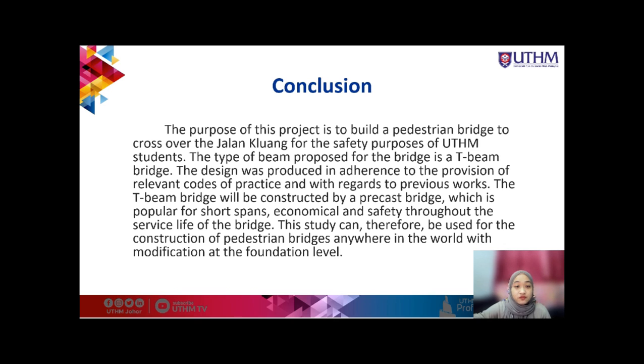In conclusion, the purpose of this project is to build a pedestrian bridge to cross over Jalan Keluang for the safety of EDHM students. The type of beam proposed for the bridge is a T-beam bridge. The design was produced in adherence to the provisions of relevant codes of practice and with regard to previous works. The T-beam bridge will be constructed as a precast bridge, which is popular for short spans, economical, and safe throughout the service life of the bridge. This study can therefore be used for the construction of a pedestrian bridge anywhere in the world with modification at the foundation level.